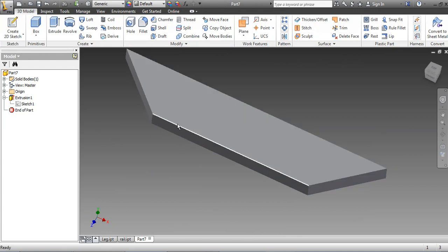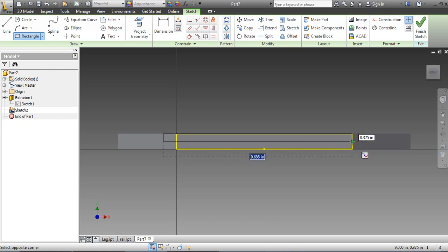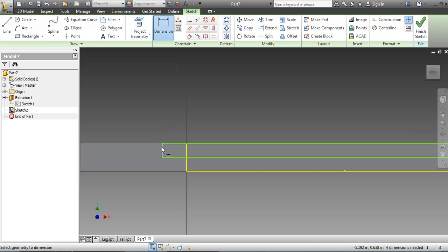Now I'm going to add a rabbet, as if we were putting a piece of glass or tile here. So go create 2D sketch, click on here, and instead of the center rectangle, I'm going to use a 2-point rectangle. And I'm not going to draw right on here because if I extrude back, it won't cut it all the way. So I'm going to come over a little bit like this, and over a bit like this. Doesn't matter the distance. And then the only thing that matters is this thickness here. We probably want it to match the glass. Maybe it's 0.25, 1/4 inch thick.